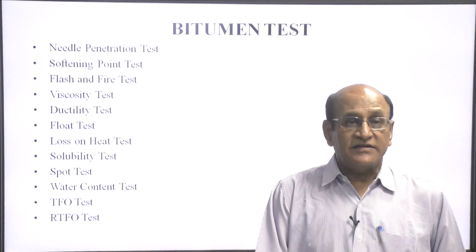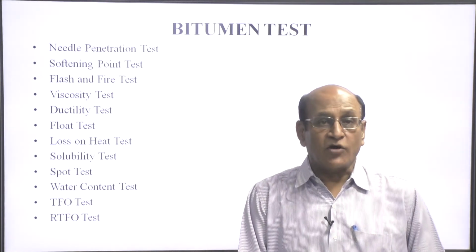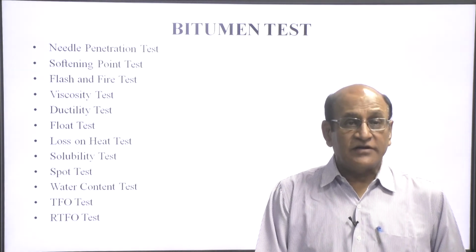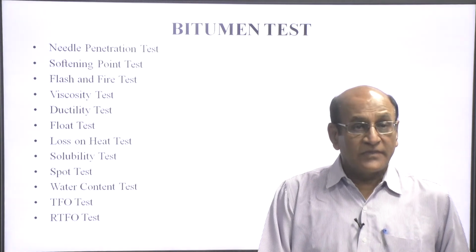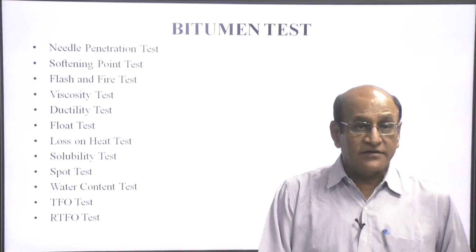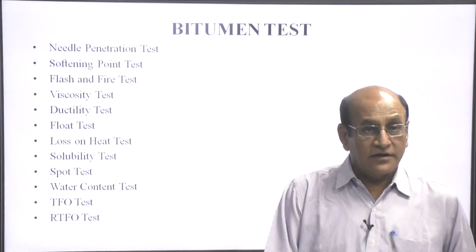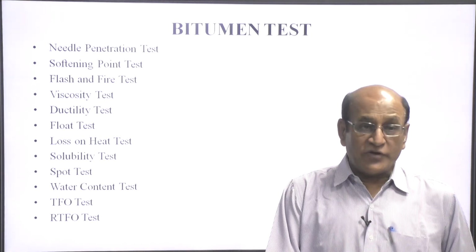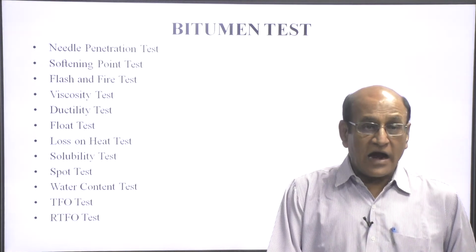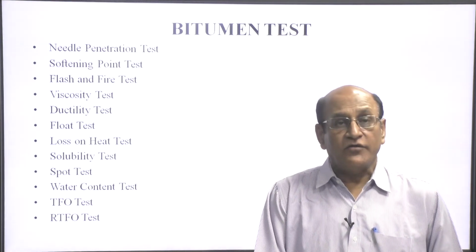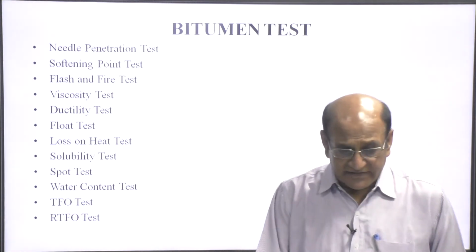First is the needle penetration test, then the softening point test, flash and fire test, viscosity test, ductility test, float test, loss on heat test, solubility test, spot test, water content test, TFO test and RTFO test. These are the tests which are generally carried out for the bitumen. We will discuss them in brief.